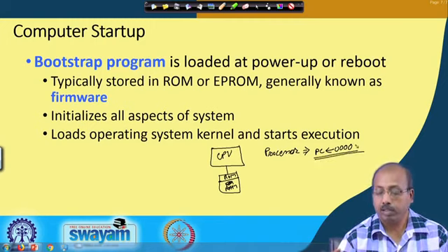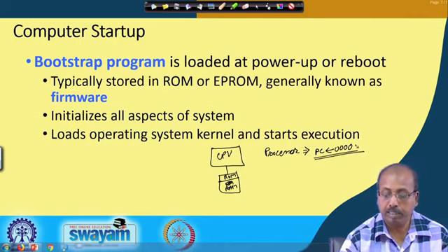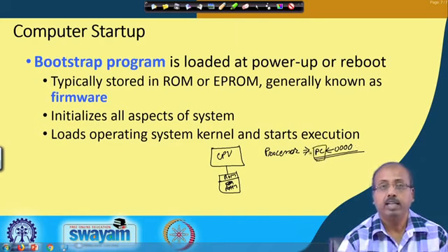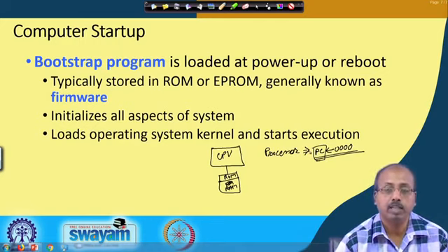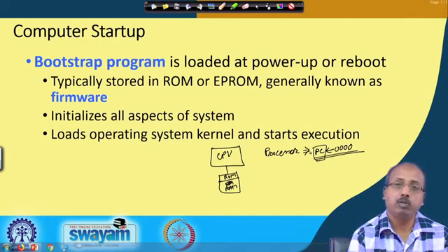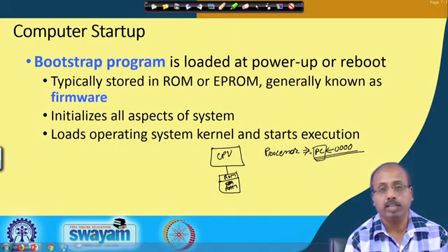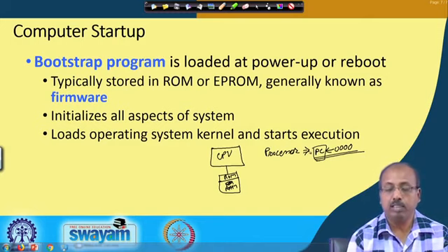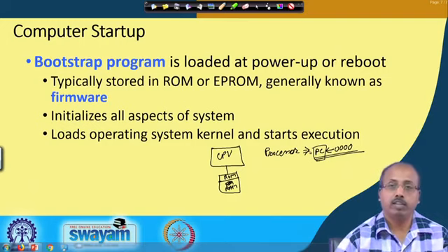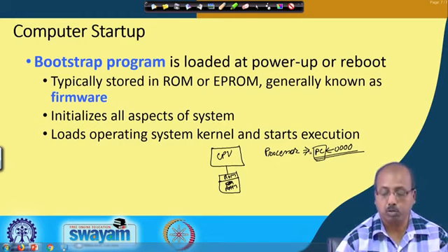And as you know, in a microprocessor, if I switch on or press the reset button, the program counter will get this value. Then at the next cycle, it puts the content of that program counter onto the address bus, and whatever be the content of the corresponding memory location gets loaded into the CPU, and that is taken as an instruction and executed. Then the program counter value is updated and put onto the address bus, so that it gets the content of the next memory location, unless the current instruction is a jump instruction. That way the process goes on.